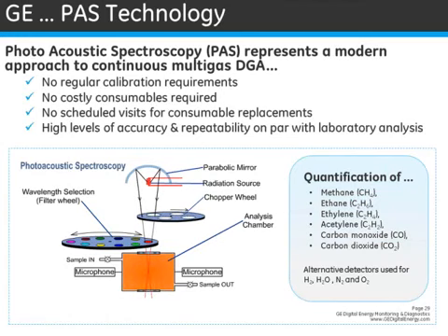Primarily, for this reason, IR techniques in general and PAS in particular have come to dominate the field of online and portable dissolved gas analysis over the last 5 years or so. It's true that PAS is relatively new for dissolved gas analysis, GE taking the first products to the market in 2004, but there are approximately 10,000 infrared-based instruments operational worldwide performing multi-gas DGA. Clearly, IR technology is emerging as the leader in this field.